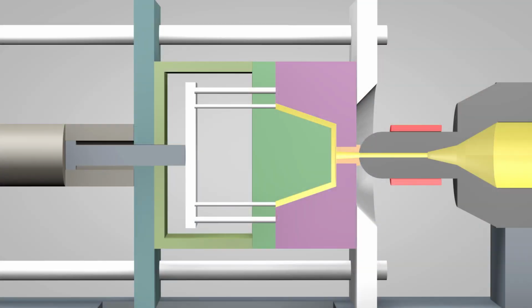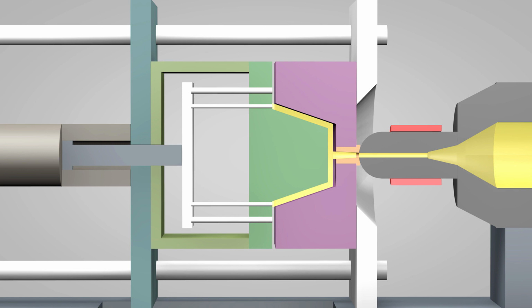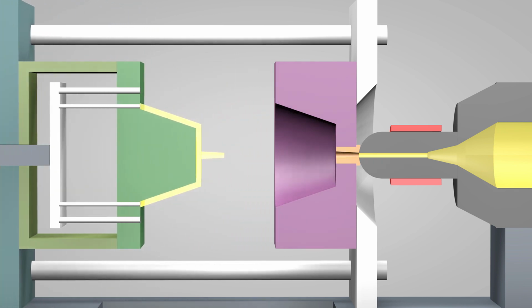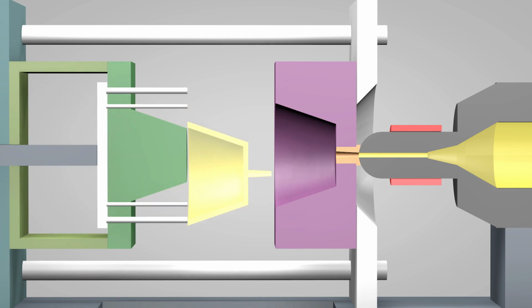As the mold opens, the volume increases without introducing air, which creates tremendous suction that holds the mold together. So at first, the mold slowly opens several millimeters to allow air to rush in and break the vacuum, and then the mold quickly opens the rest of the way so the part can be removed.